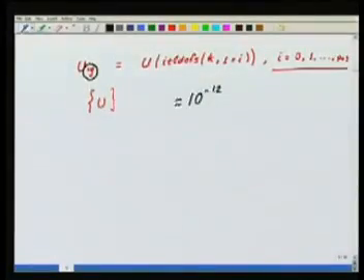If these nodal values, or the point values, that is the degrees of freedom, are equal to the exact solution, then we can say that at least for the cases where the exact solution has to be equal to the finite element solution, my finite element solution is the correct one. Okay, so this check has to be done element by element, and we should output the values and check.